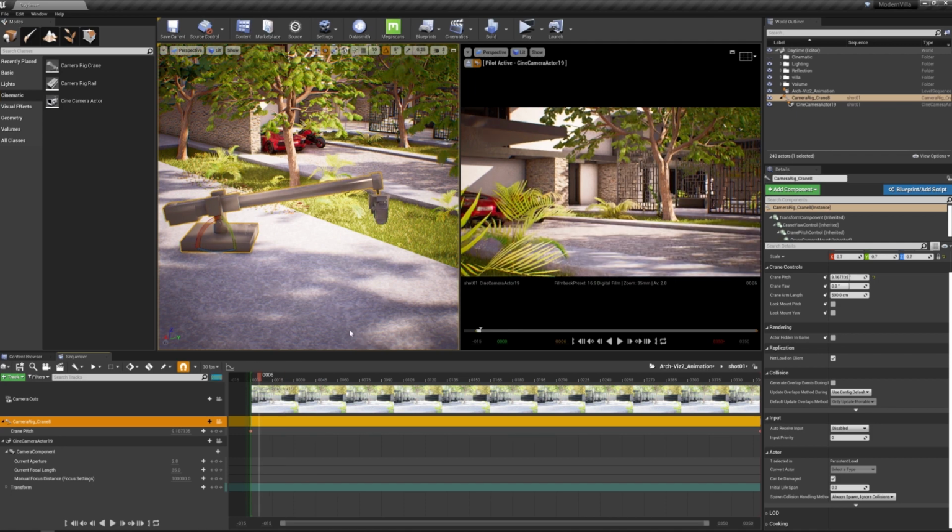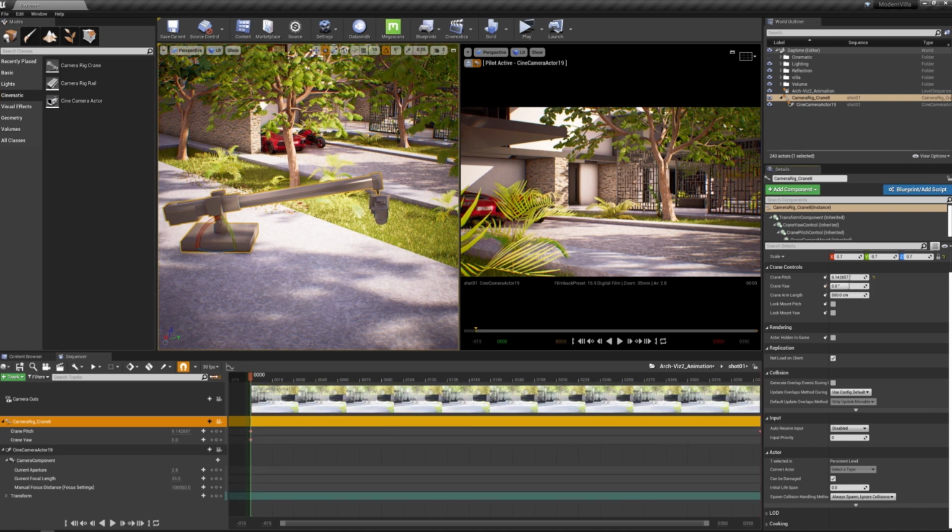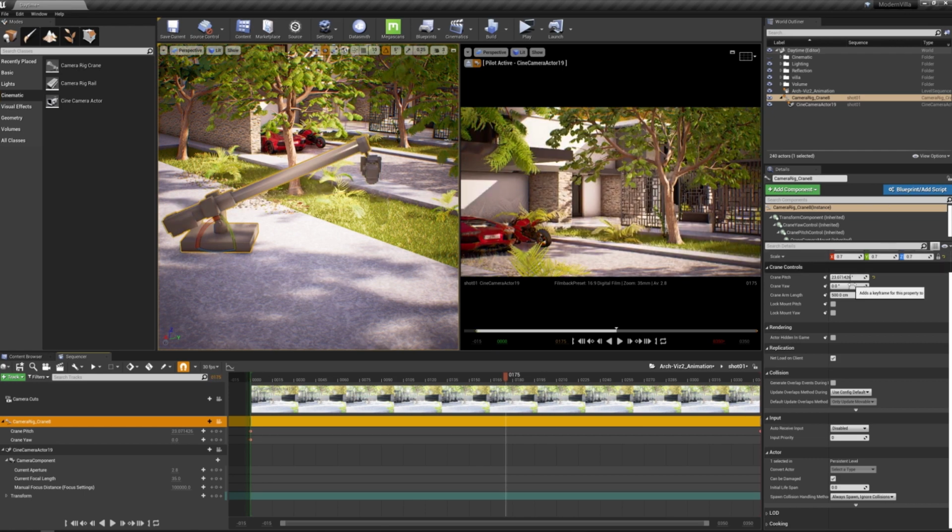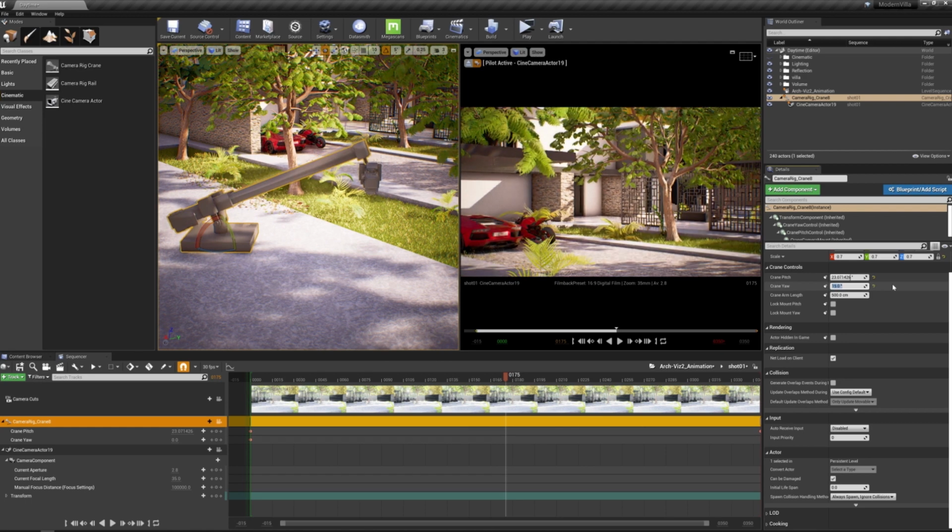We also want to adjust the yaw of the crane a little bit, so I'm going to head back again to 0, and start the yaw keyframe at 0 at this point. Then move, let's say, halfway in, at frame 175. I'm going to push this crane to, let's say, 15, on the other side actually, minus 15.